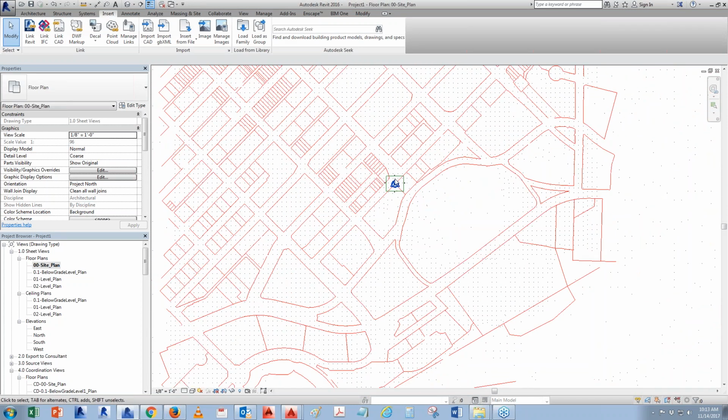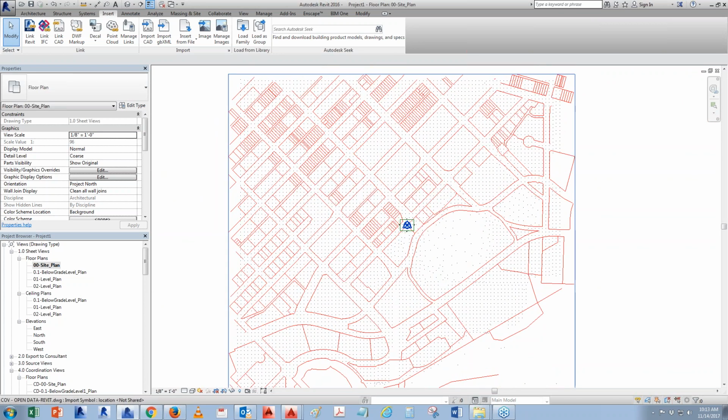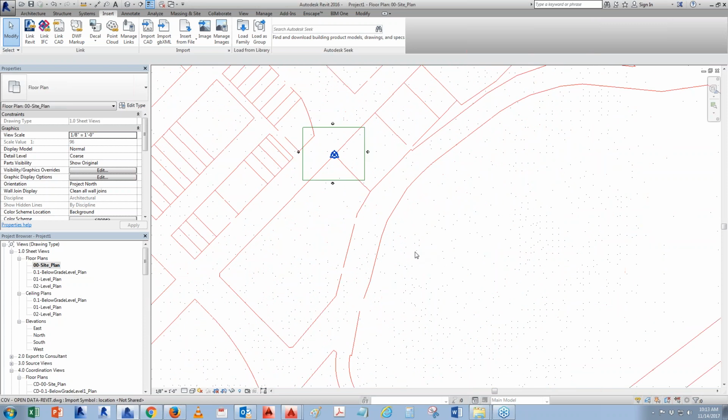There we go. Now, you notice that sometimes Revit will translate the point, sometimes it will not. So it really depends. Can you use this as your data point? You can. Sometimes it will work, sometimes it will fail. So a lot of the time I don't encourage it, because sometimes the points can disappear. I'm noticing in more and more projects that points never show up when you need them, and when you don't need them, they do show up. So it's kind of 50-50.